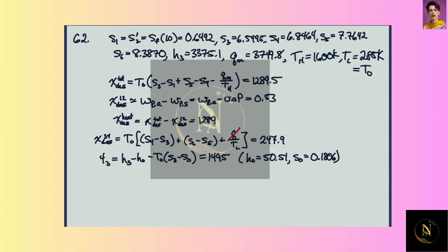Once we got the entropy at the inlet, we assumed that the entropy at the outlet was the same as the entropy at the inlet, and then we got the isentropic enthalpy, and then we found the real enthalpy. So then we need to go back and find the real entropy, which I've done here for some of the exit states coming out of the different devices. That's simple enough that I think you can do that by now. Again, we have two thermodynamic properties at every state, so we can find whatever else we need.